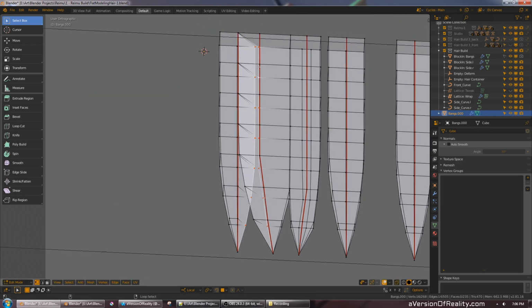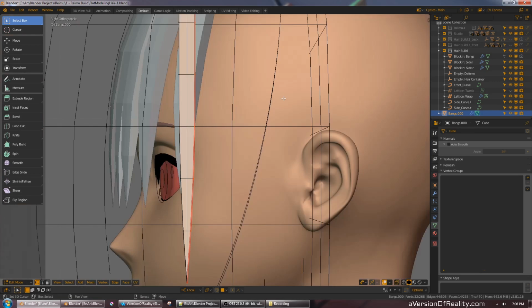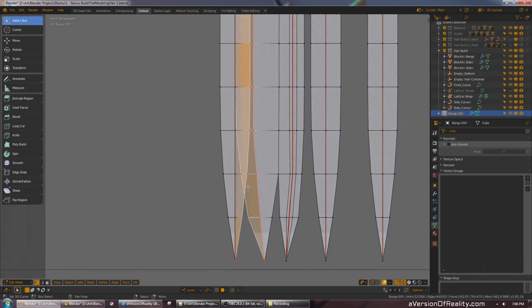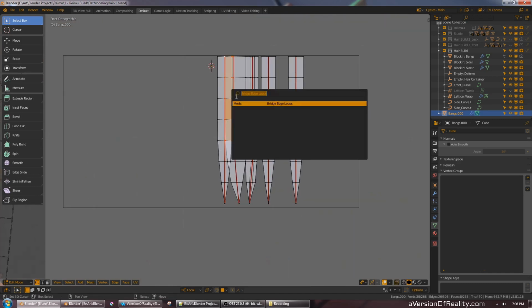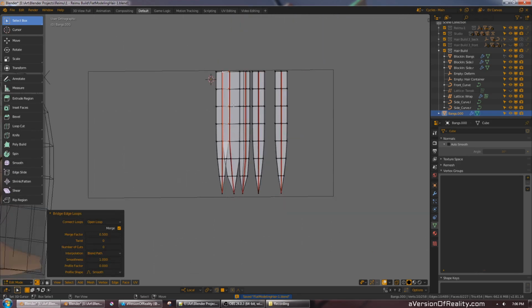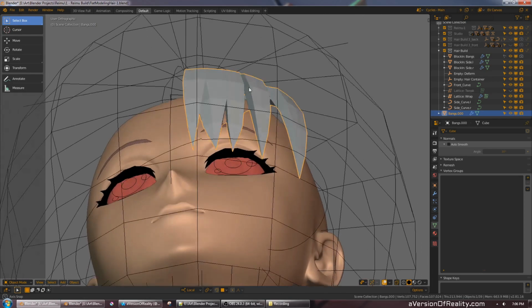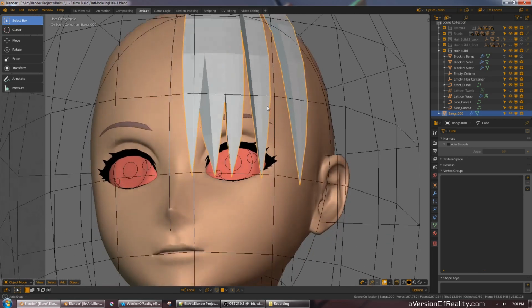Now, when making this selection, I have to watch that I'm selecting the right areas. Then I will deselect all the points that we don't want to be bridged, and fire the bridge command again. There you go. Now we have a diagonal bridge instead of a flat one.